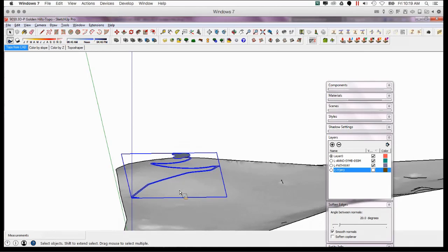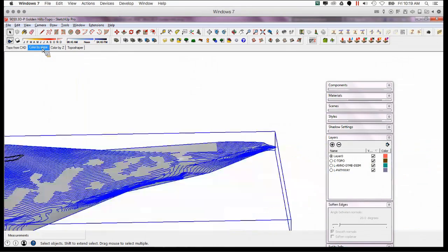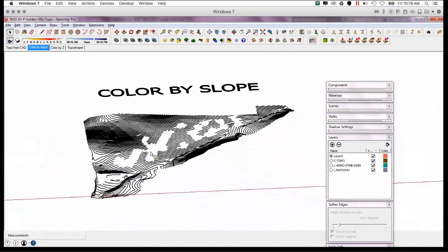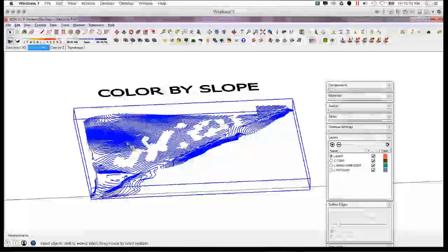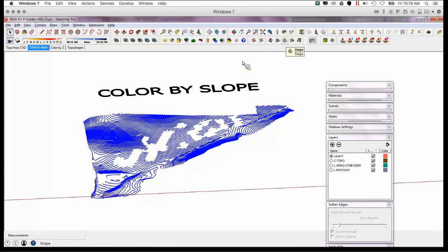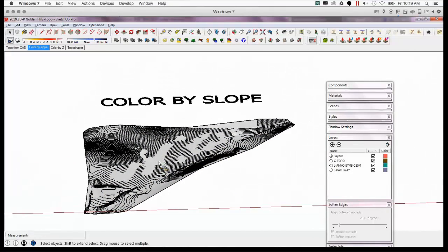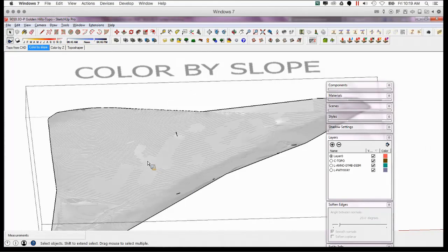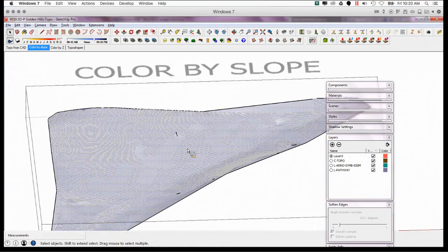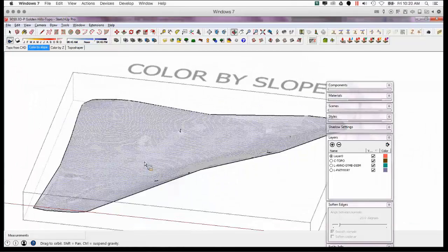It's insane. So being able to get your actual stuff, the terrain and the mesh here, we're going to do this one more time here. We will explode this line work, and let me get a terrain. These next two tools that I want to show really quickly are color by slope and color by Z. And Chris Fulmer has created these, and they are pretty slick little tools. What's interesting about this color by slope is you can start to get a sense about how steep things are. It's not going to tell you the actual percentage of slope, which is a little bit of a bummer.